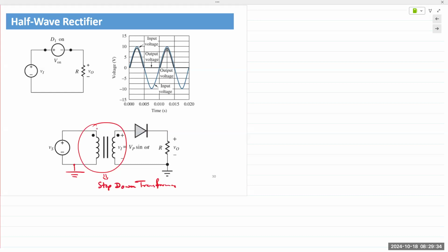And that's how an actual DC power supply works. Even today, the devices that we use, the chargers that you plug into the wall, for your mobile phones, tablets, laptops, they still function on this exact principle. You have a transformer at the front end that steps down the voltage.